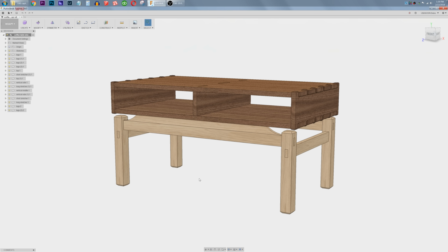The second thing is I use keyboard shortcuts a lot in SketchUp. I still use them a lot in this program. They will always save time. And then also something that this program has that SketchUp does not is this very fast right-click menu. I don't know what this is called, but if you right-click anywhere, you get a menu, and if you go in any direction, you get basically like a piece of a pie. Like I said, I don't know the technical term for this in this software, but I call it a clock wheel. 12 o'clock always repeats your last command.